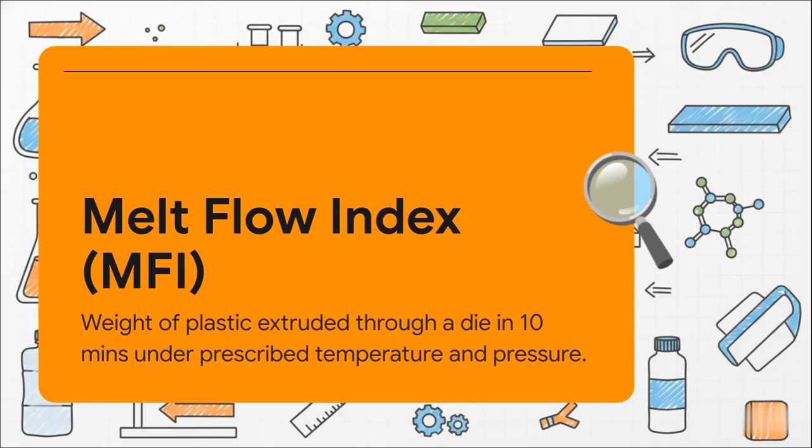Okay, so in plain English, it's basically a measure of how easily the plastic flows once it's melted. Exactly. It's a gravimetric flow rate. And here is why this is absolutely crucial in the real world. MFI is an inverse measure of molecular weight. So a high molecular weight plastic is kind of thick, it's more resistant to flow, which means it has a low MFI. On the flip side, a low molecular weight plastic flows super easily, giving you a high MFI. Processors rely on this exact number to set up their injection molding or extrusion machines correctly.